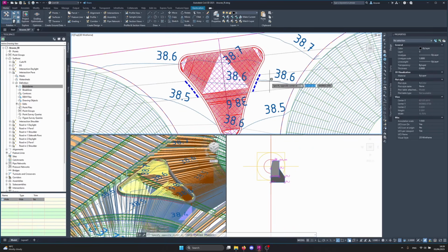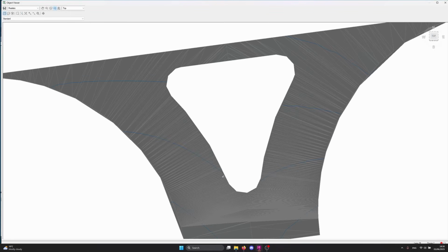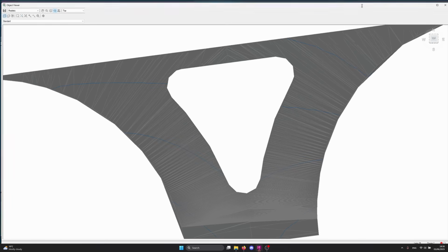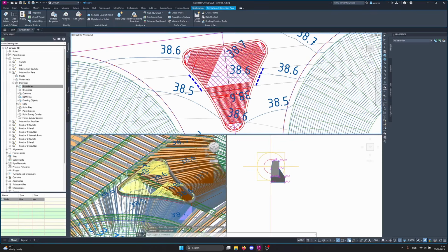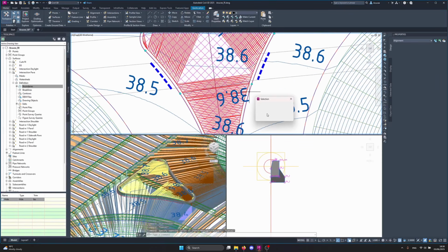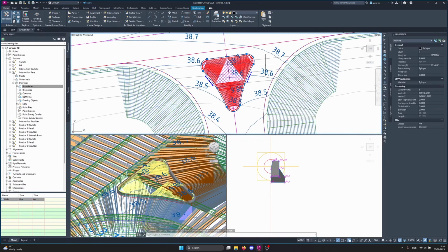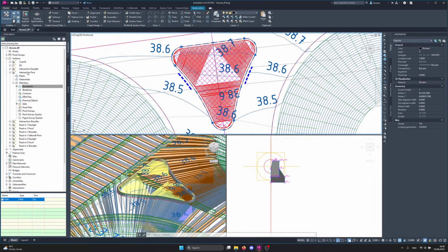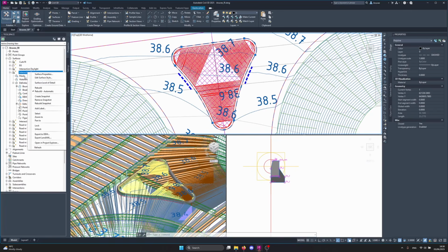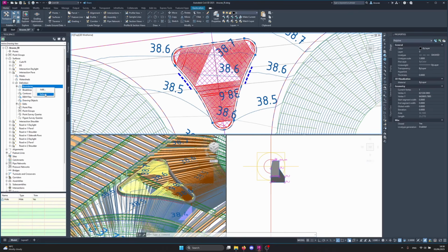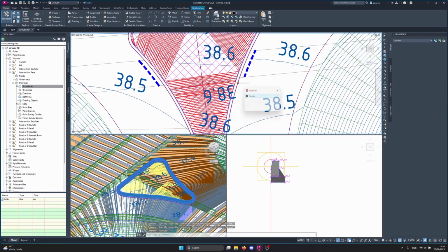So as you can see right here, I have this intersection, right? And the polyline is used to hide the surface below the pedestrian island. Simple as that. And you can add the boundary by first of all making a polyline, choosing your surface, and in the definition boundaries you can just add a boundary. It's a height type. So yeah, about the boundaries.